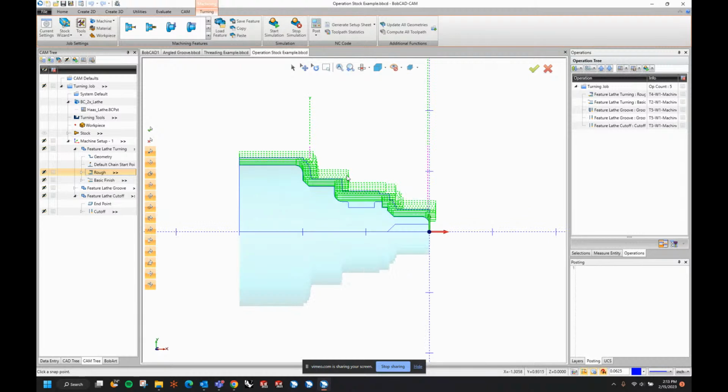But besides those minor details, those templates save tons of time. I mean, this is primarily 90% of the jobs that I've done turning. Drills are usually easy to add. I don't typically add those through the templates. The other thing you could do is make a job without stock defined, load all your tools and make that a template. So whenever you start a new job, it just has your tools. That way you're not having to load a crib every time.